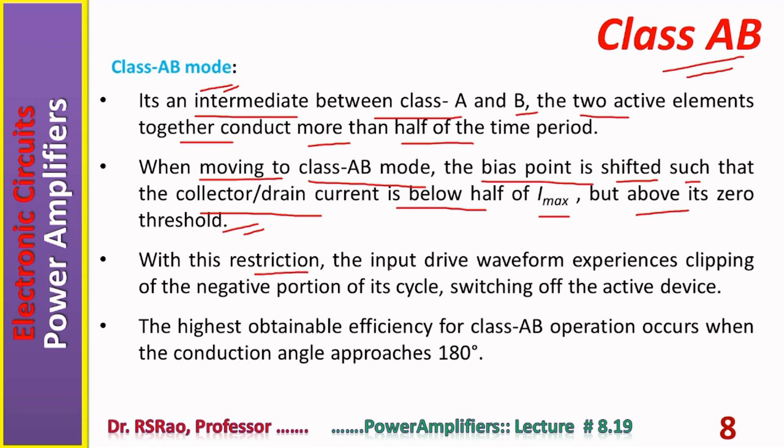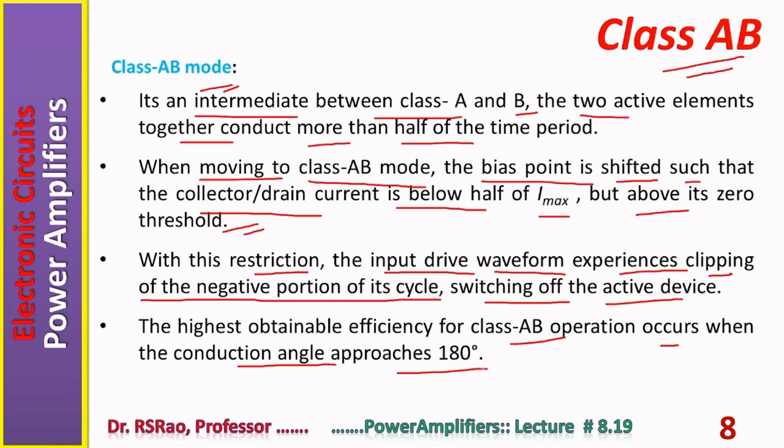With this restriction, the input drive waveform experiences clipping of the negative portion of its cycle, switching the active device. The highest obtainable efficiency for class AB operation occurs when the conduction angle approaches 180 degrees.